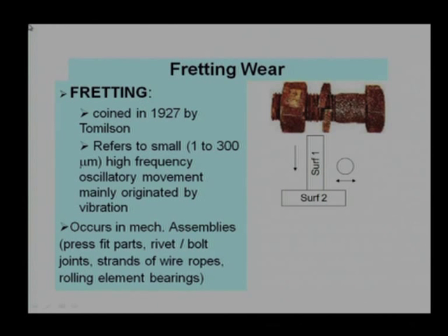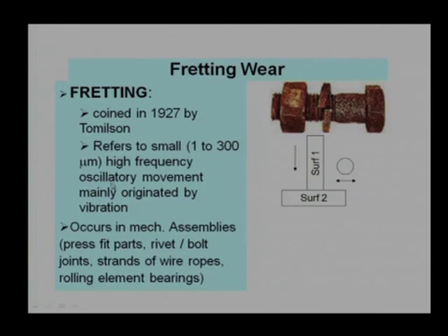And when we are talking about fretting, we are talking about very low magnitude, high frequency vibration. Energy is coming, but at low magnitude or low amplitude, in terms of 1 to 300 micron, so it will not be detected easily. Some machine is running and we will not be able to see the vibration as such, but a 1 to 300 micron vibration between two components is happening, and that is causing the fretting wear. Is this a high frequency? Low amplitude. So, overall energy comes from the higher side. In addition to that there is oscillatory motion also.